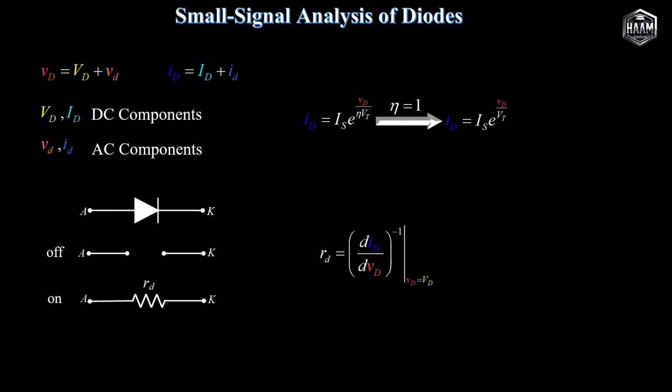By definition, the small signal dynamic resistance is the partial derivative of diode voltage V sub D with respect to diode current I sub D. Taking the derivative of the diode voltage yields the dynamic resistance, representing the total incremental resistance denoted as R sub D. Normally, since current is expressed as a function of voltage, we differentiate current with respect to voltage, evaluated at the designed constant operation point Q. This defines the dynamic conductance.